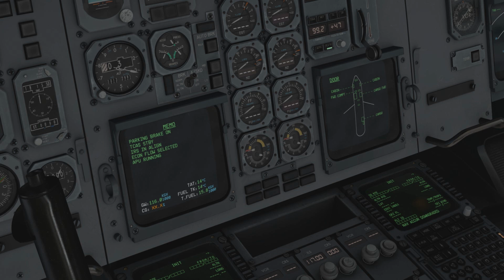This aircraft is already advanced enough to go, I know what it is, this is what it is, and this is what you need to do to fix it. So the old school way of doing it is you pull out a book, or you call it a checklist, or whatever you want to call it, called the Quick Reference Handbook, and it has all of the procedures in, and you would manually look around the aircraft and go, oh, I think this has gone wrong, and agree between you, yes, it's this, and then you would get the book out and you would action the items on there.